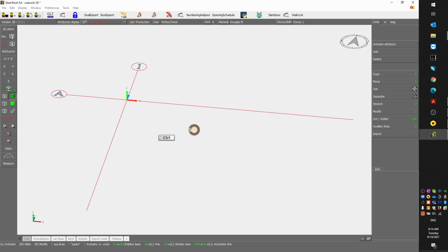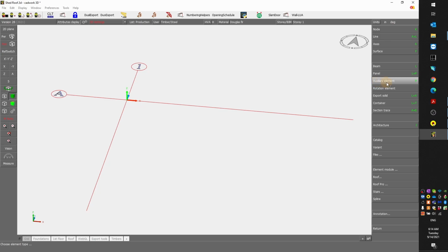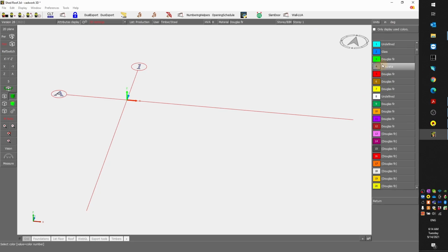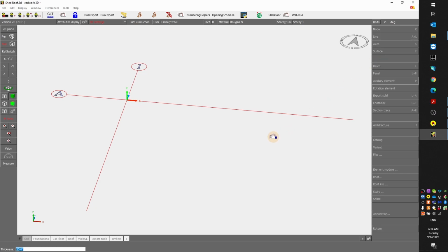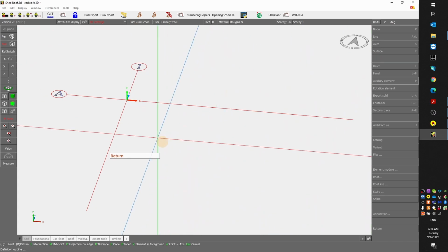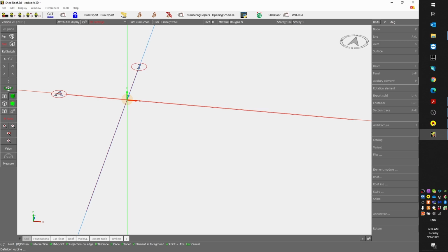So now we have an empty file, and we are going to start with the slab. The slab is 65 feet long by 46 and 8 inches thick. So we are going to add an auxiliary element. It's a concrete, and we will pick the name predefined called slab. Then the thickness of the slab is 8 inches. And I'm going to start from the origin here.